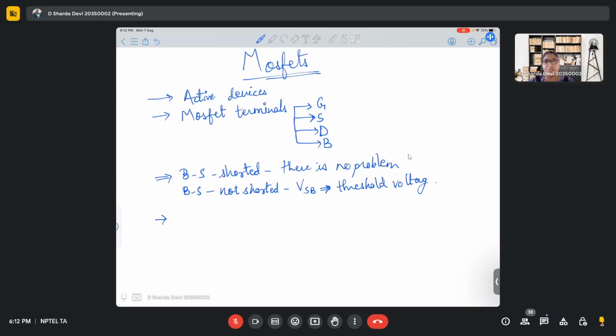If the threshold voltage of a transistor is high, then the leakage will be low. But if the threshold voltage is low, your current will be high, but leakage will also be high. So there are trade-offs, and when you want an optimized circuit, you need to consider all these trade-offs and design your circuits accordingly.